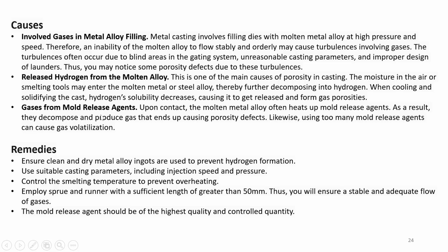Gases from mold release agents. Upon contact, the molten metal alloy often heats up mold release agents, and as a result, they decompose and produce gas that ends up causing porosity defects. Likewise, using too many mold release agents can cause gas volatilization.